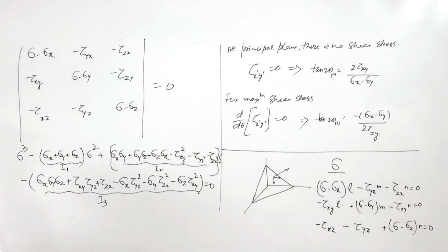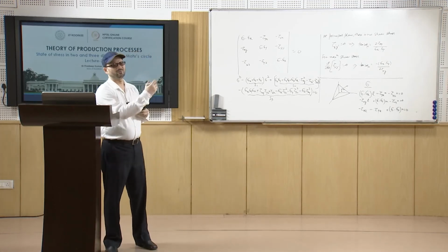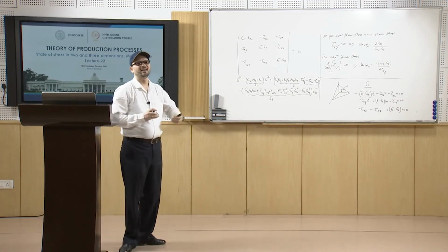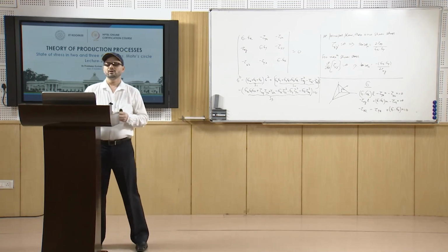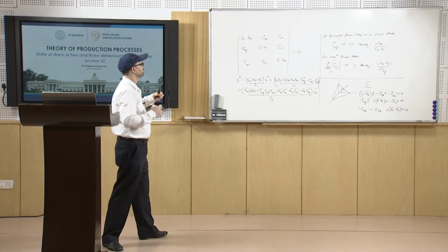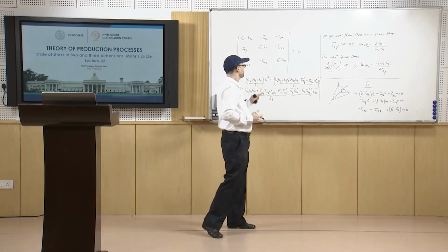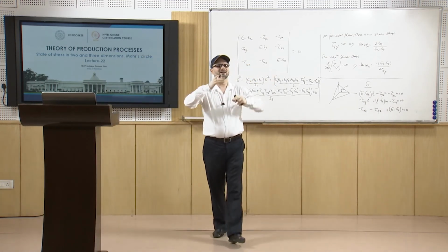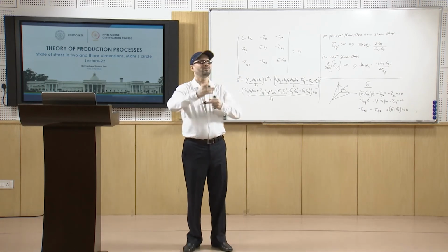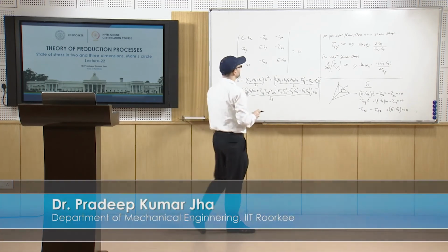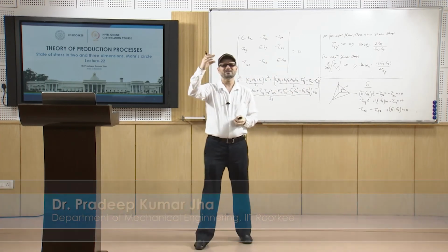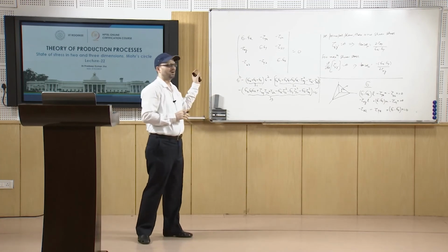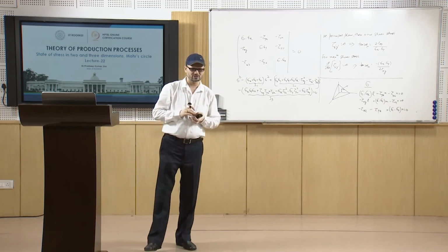So, these are the stress invariants, which will be used when we discuss stresses in later lectures. Further, if you resolve for a plane at a certain angle, there can be further analysis, and you can see how to find, for any plane with certain direction cosines, the maximum shear stress.